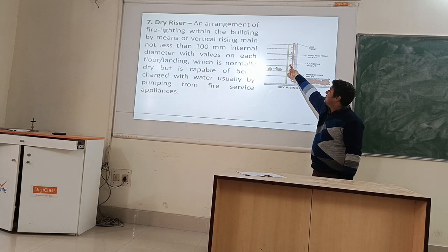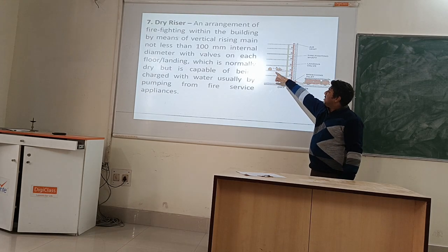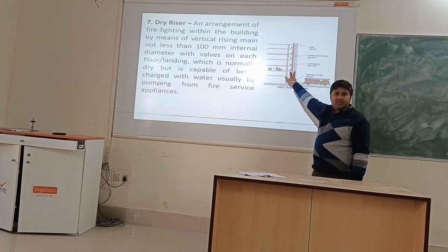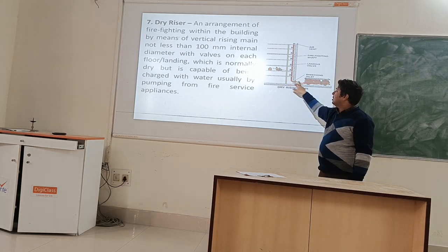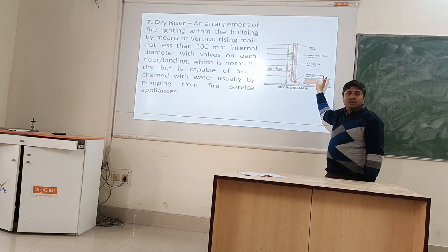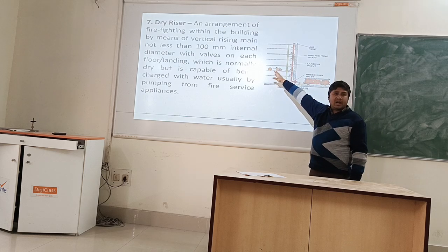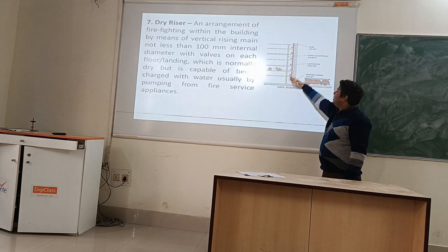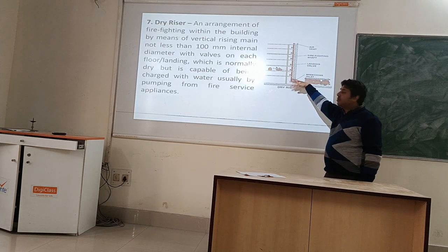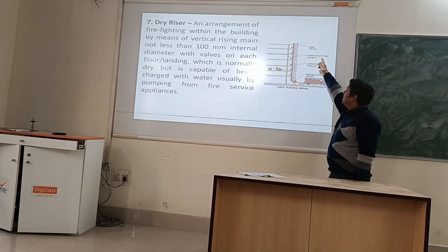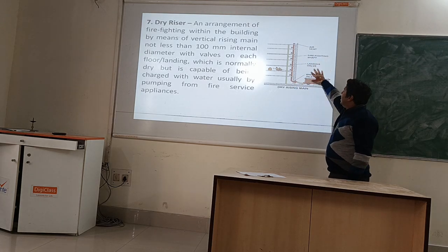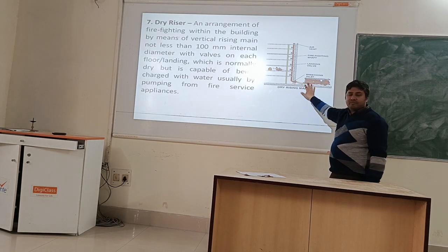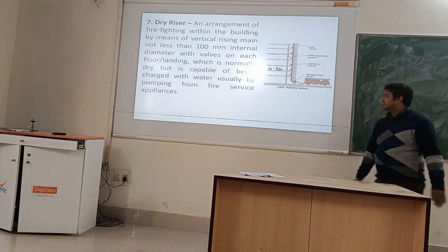From the landing valve, at any portion where there is a fire, the firefighter can take the pipe already present in the building and carry the water from the fire truck to perform the extinguishing operation. There will also be a firefighting shaft for movement of people, an air vent, and most importantly the landing valve. This type of riser is called a dry riser.